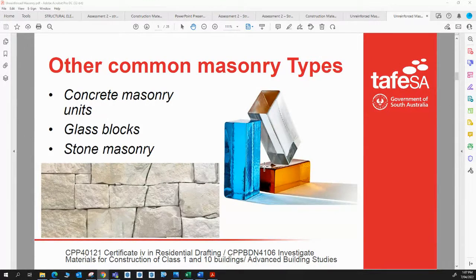I've seen issues in buildings before where slightly uncured concrete bricks have been used with fresh mortar mix, and you get a lot of shrinkage over the wall as they continue to cure, and that can be problematic as well. I've certainly seen plenty of evidence of that in building practice. So not such a fan of them, and it's probably one of the contributing reasons why you don't see them used commonly in your housing estate.